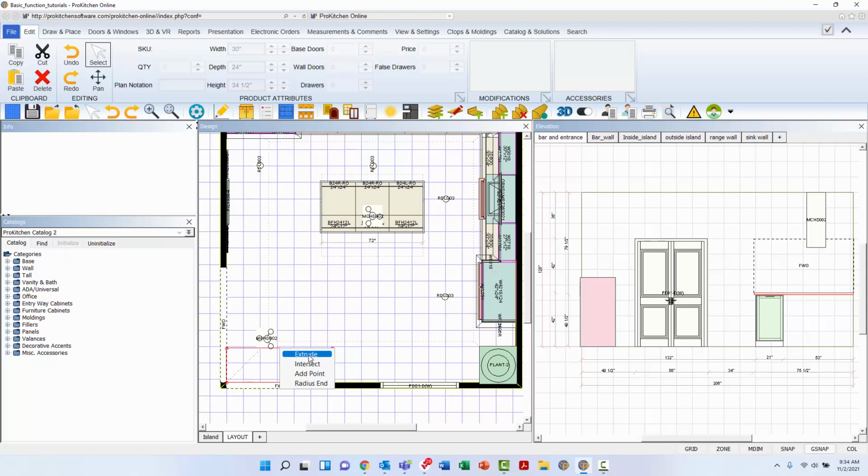When you left-click the Extrude option, a little point will follow the mouse along the line. This point will be the starting point of the extrusion. Move the mouse to the desired location on the line and left-click once. Then, move the mouse into or beyond the existing countertop, creating or reducing depth, and over to the opposite end of the edge to control the width of the extrusion.